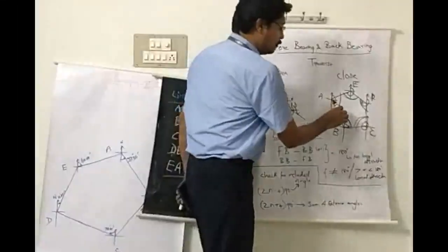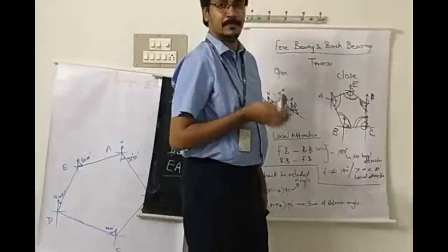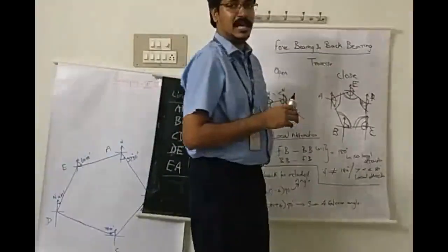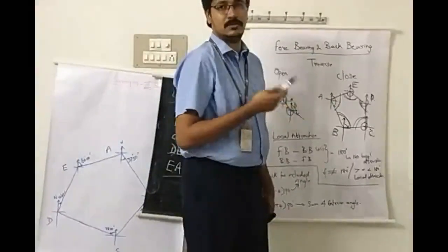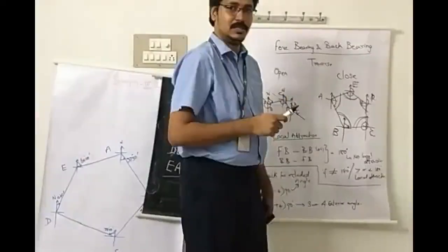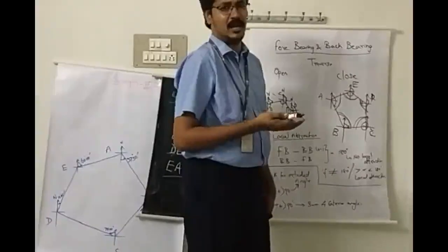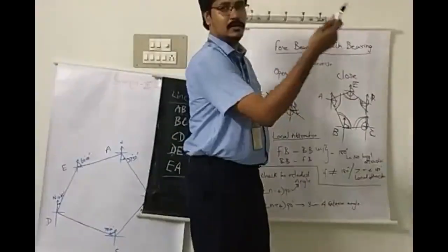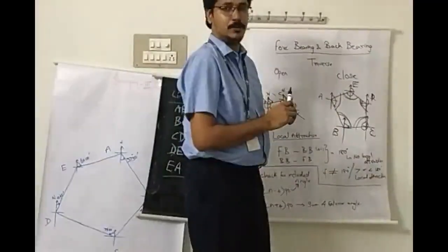If you are able to measure all the distances and angles, then you are able to get the area of the particular land. When the area becomes large, compass surveying is supported or can be used. With a chain, we can measure the linear measurement, but not direction. It cannot give the direction. So the compass can give the direction and it can go for a longer area also. So compass surveying can be used, right?